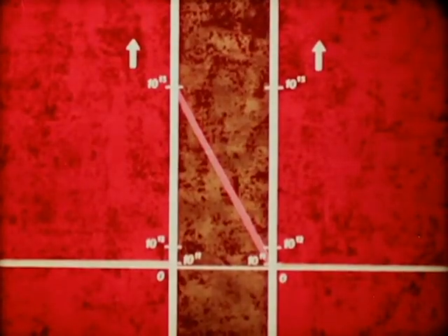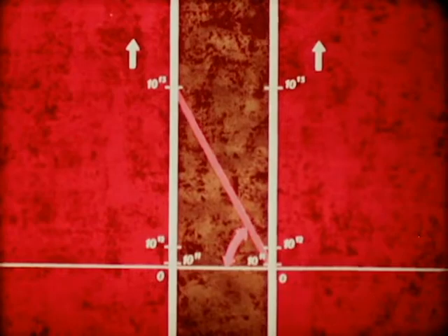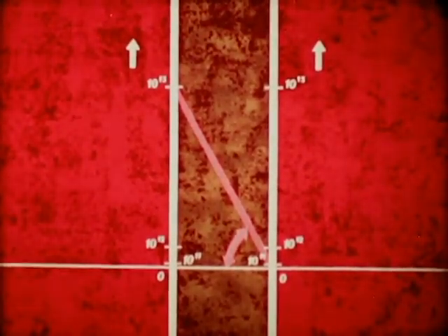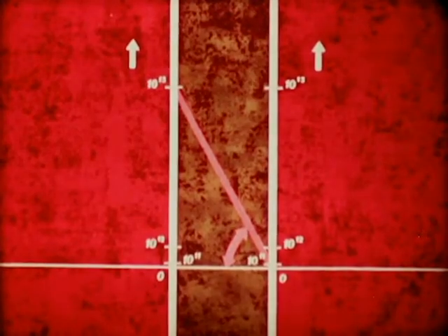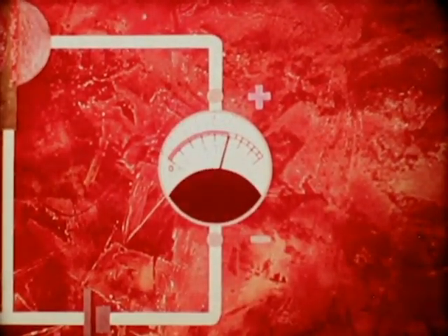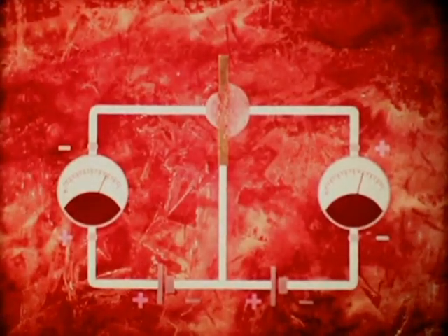The concentration curve of the holes in the base also indicates a large flow of holes into the collector. As we know, these holes originate in the emitter, flow through the base, and are absorbed by the collector, giving rise to a large collector current. In this configuration, the base current is the sum of two small currents.